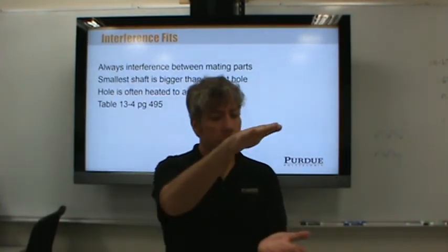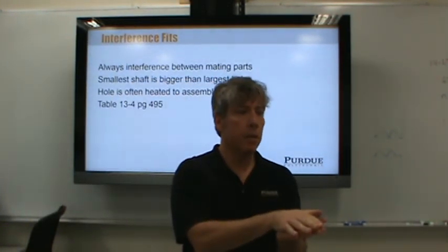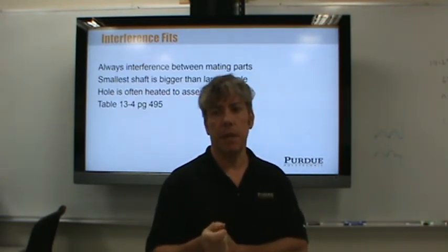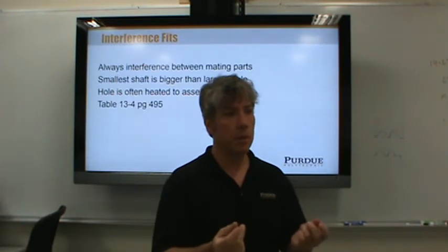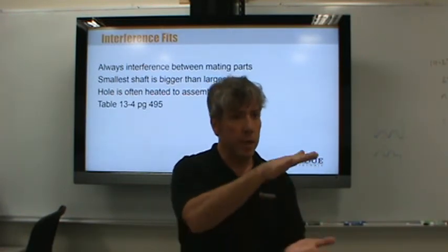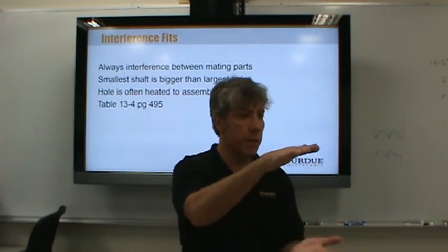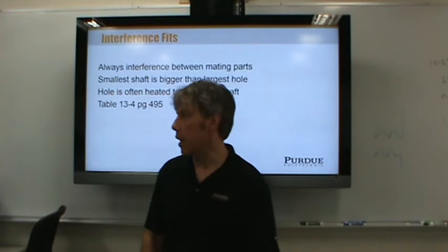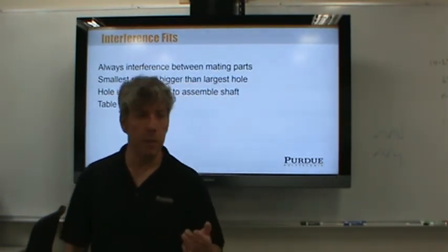When you want to mate a cylinder head to a block, you don't just use bolts to do it. That's a bad idea. The bolts are not that precise. Instead, there are dowel pins that are used that are typically specified as a transition fit, and they have to be pressed in, and the action that presses them together is typically just bolting the head onto the block. Sometimes they're clearance fits. It just depends on the manufacturer.